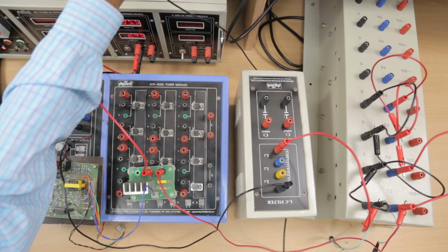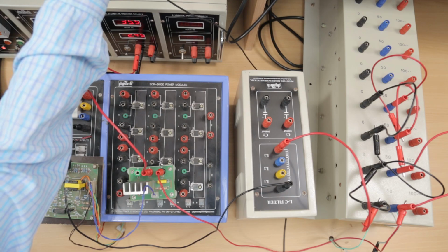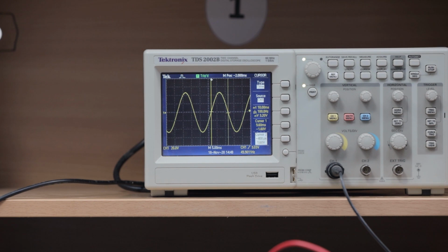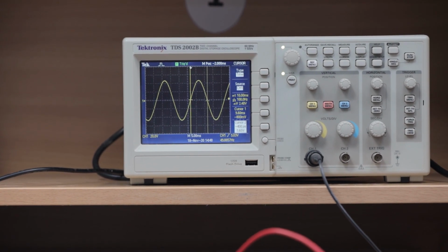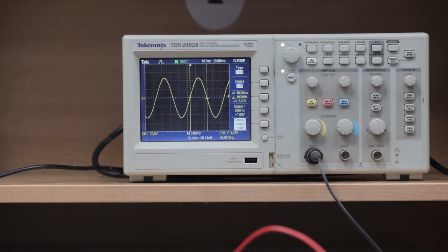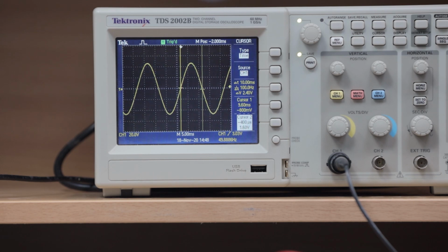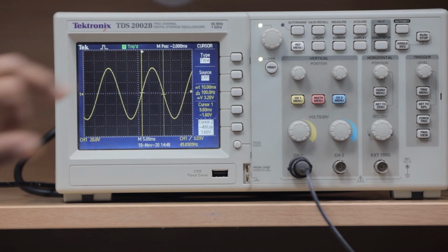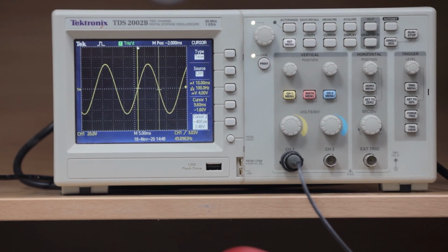Now you can observe, first, using the cursors, that for completing a half cycle delta t is 10 milliseconds. When the firing angle is 0, a half cycle of 180 degrees takes 10 milliseconds. So you can calculate for 45 degrees, 90 degrees and 120 degrees. This value divided by 4 gives 2.5, which is 45 degrees.